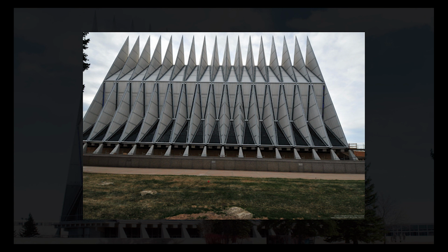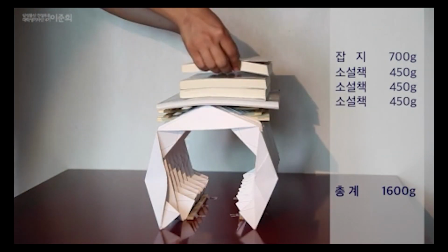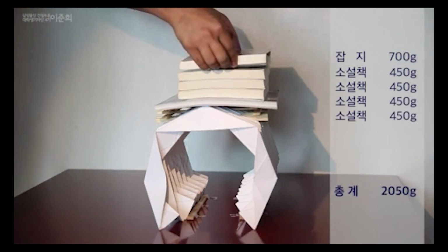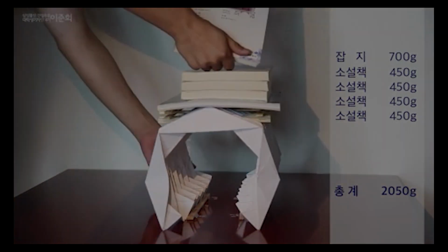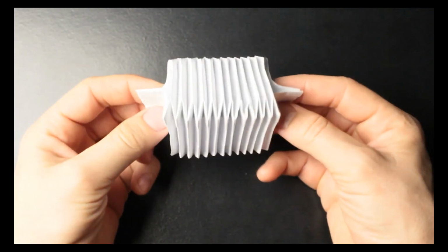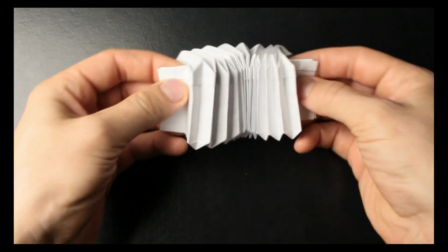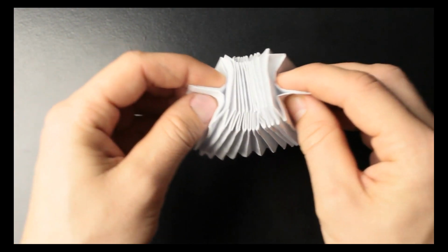the entire structure. Each member within the folding system plays a vital role in this process, transmitting compressive forces to the exterior while receiving tensile forces internally. This arrangement, coupled with the large structural surface area inherent in folding systems, facilitates efficient load distribution. However, it's worth noting that while these structures excel in distributing vertical loads, they typically exhibit weaker resistance to horizontal loads. When subjected to horizontal loads, folding structures may encounter challenges in withstanding the applied forces, resulting in bending moments